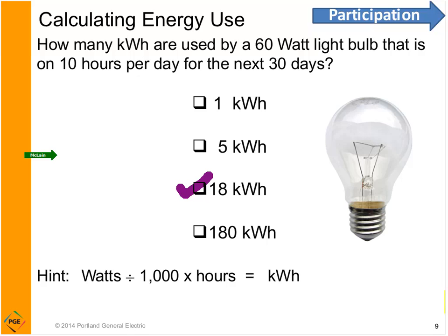One bulb doesn't use a lot of electricity, but one customer I spoke with was an auto dealership. This businessman counted the number of bulbs that lit up the area inside and outside his sales lot and had about 500 of these 60-watt bulbs, which added up to 30,000 watts, or 30 kW. They were on quite a few hours each month, 360 hours a month. So at 8 cents a kilowatt hour, he was spending $864 every month for these lights. So my examples might be small, but at most businesses, the number of lights would be substantially higher.